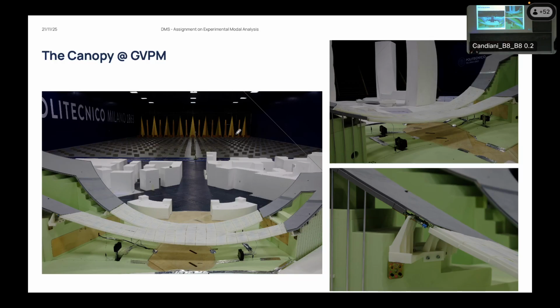Structural damping is something that is part of the structure itself. So you can decide the mass, you can decide the stiffness, you can decide everything, but then for the amount of damping, you can avoid some solutions that for sure will be a source of damping, but then you have some inherent damping that will still be there. So it's very important to be sure that before starting any test in the wind tunnel, the elastic model is really compatible in terms of dynamic properties with the structure we are going to match. Okay. Otherwise, all the results you are getting are not really representative of the full-scale structure.